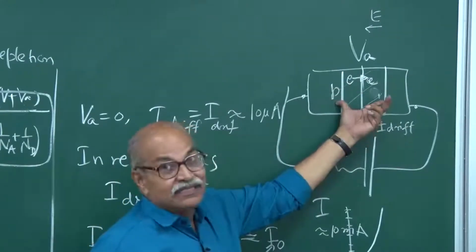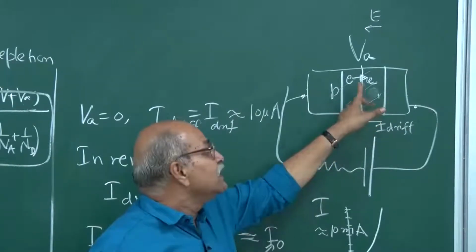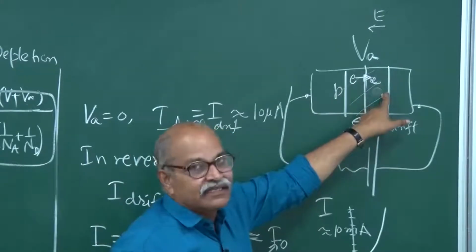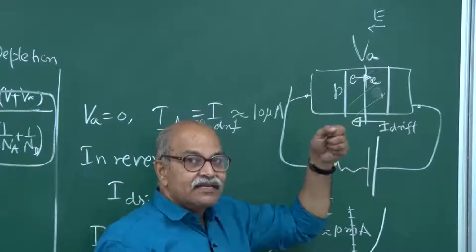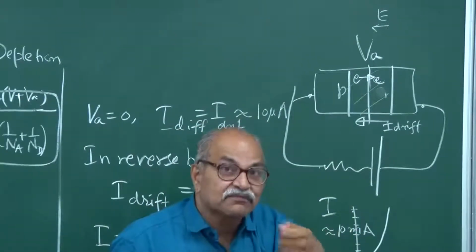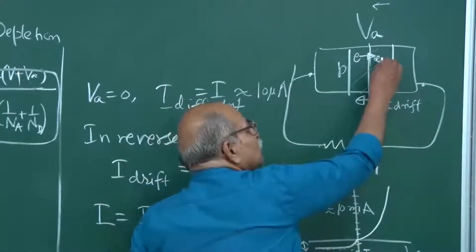The electron is going in this electric field, it is accelerating, it is gaining kinetic energy, and the depletion region is wide. Therefore, it has sufficient time also. So, it can gain so much energy in this depletion region because of the effect of this electric field that it can knock off an electron from the bond, and this electron can produce a new electron hole pair.